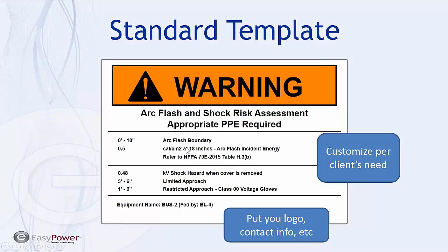So in this particular case, what NFPA recommends or suggests is that you refer the operator to a table where the PPE is described, and that the operator or technician is responsible for layering up to the energy level that's required. So the complaint, or the suggestion, is: well, since no one's going to carry around a copy of NFPA 70E, what does this really do?